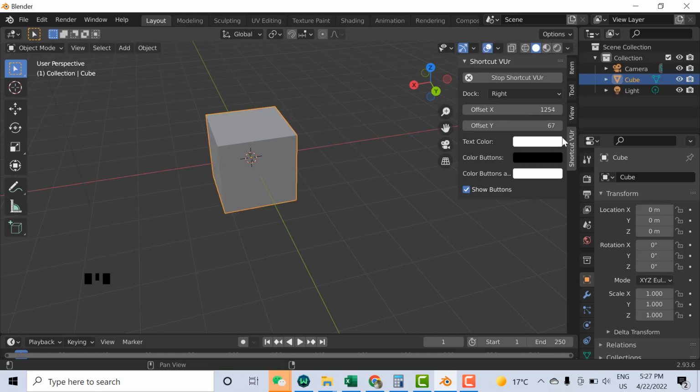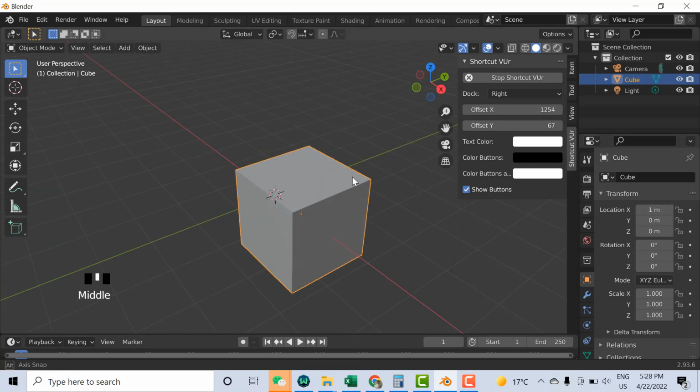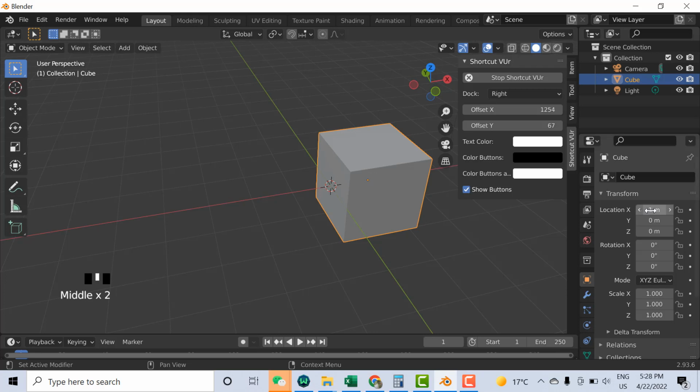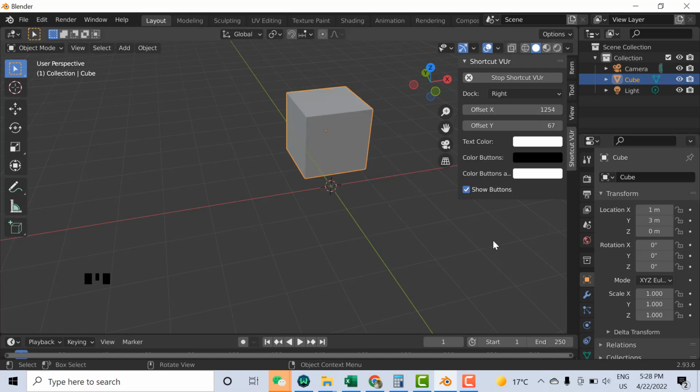So what you need to do is, on the right side here you see the different options. Click on object properties here. Now at the top you can see the location. You can set the object location to 1 meter on the x-axis, and keep Y and Z at 0. Just press enter. It goes 1 meter on the x-axis. Like this. If I say y-axis 3 meters, I write 3, you can see. Now here you can get the exact position that you want.